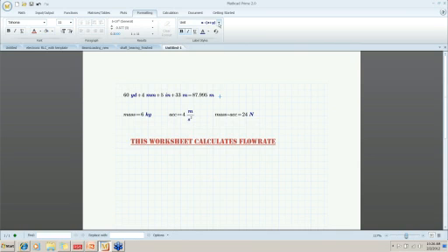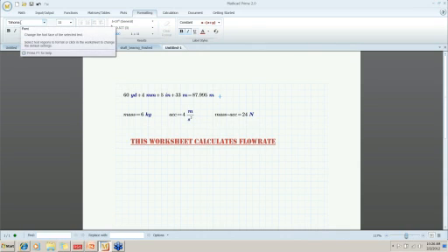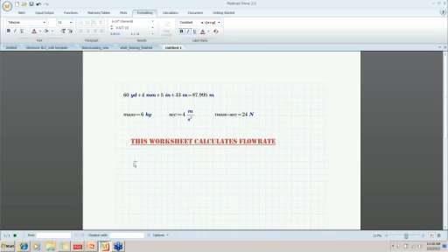Now if we go down to constants, if we have any constants in our worksheet, I think forest green is selected, but let's make them this dark red color, and we'll bold them. You can't manipulate the size; the size is what it is, and the font is inherited from whatever font is set here. So now constants are maroon.